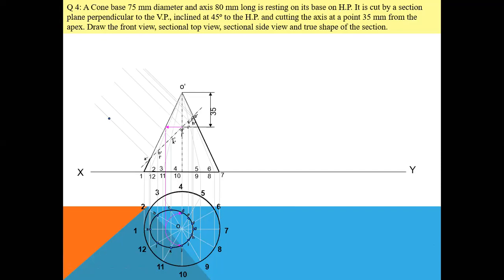Fine. Likewise, if I want to get this point B, identify this point B in your top view. Next, I will take my compass and measure B to this horizontal reference line XY, this much length. Then I will place my compass at this point, and on this reference line, I will cut an arc. This will be your point B.